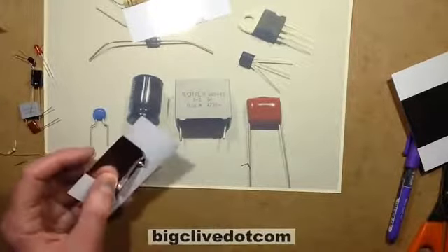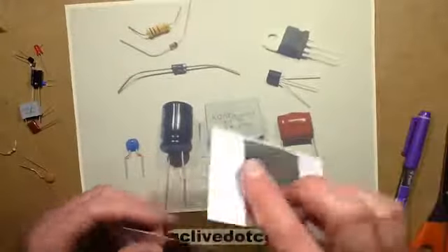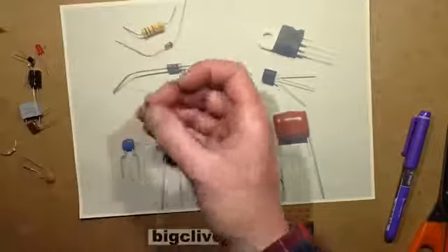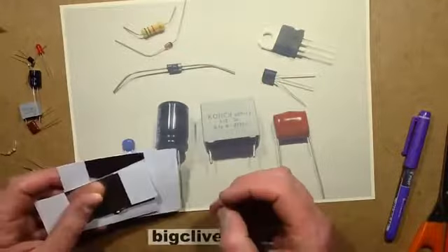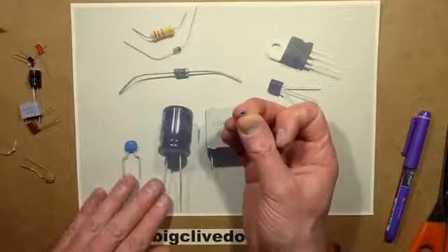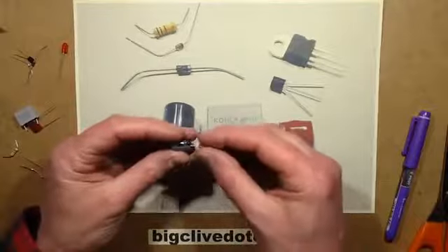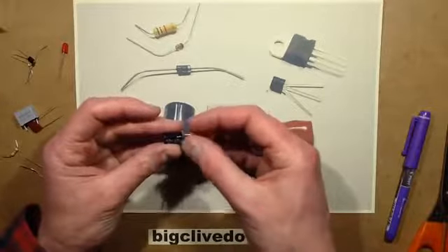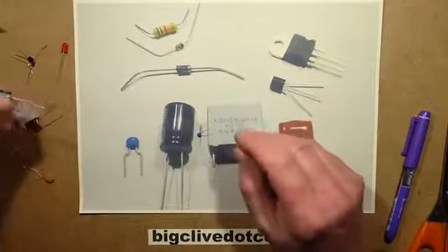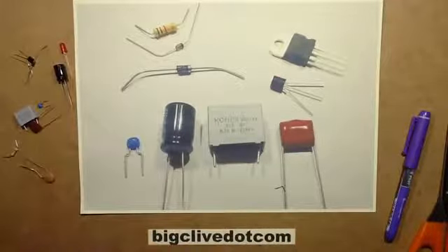And to get the value of capacitance up, in reality, for components like this little one, keep in mind that I managed just a couple of nanofarad. This one is rated 100 nanofarad. And if you look at things like this, this is an electrolytic capacitor which is rated 470 microfarad, which is a massive capacitance. And to achieve that, let's get the notepad back in again.